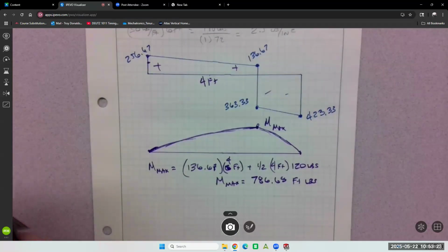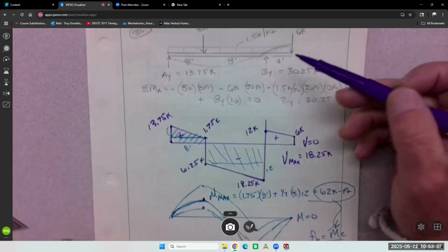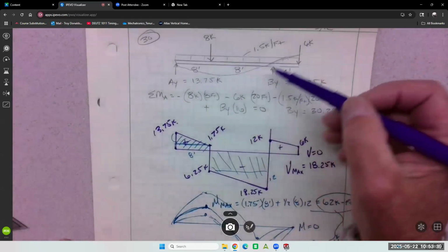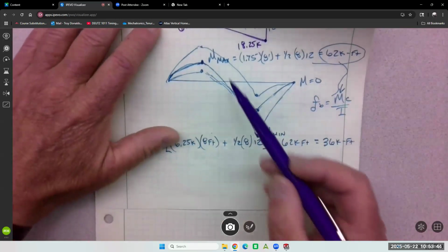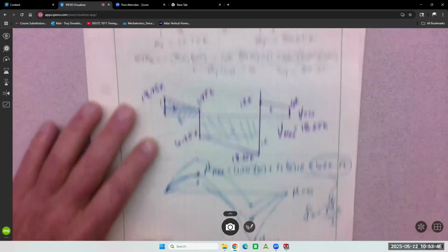Just mean in one beam, we can have only one maximum moment, right? On this one. But in real, we can have two. This first one we did. So this beam, because it changes concavity in the deflection, it definitely had 2 maxes. Yep. But not every beam will.